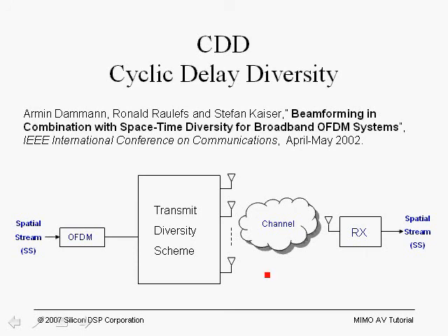For example, as we've discussed in MIMO systems, we have multiple output, multiple input, multiple transmit chains, multiple receive chains, and usually prior to using MIMO, we need to train the receiver in order to obtain an estimate of the channel. We also have to do, prior to that, acquisition and packet detection.